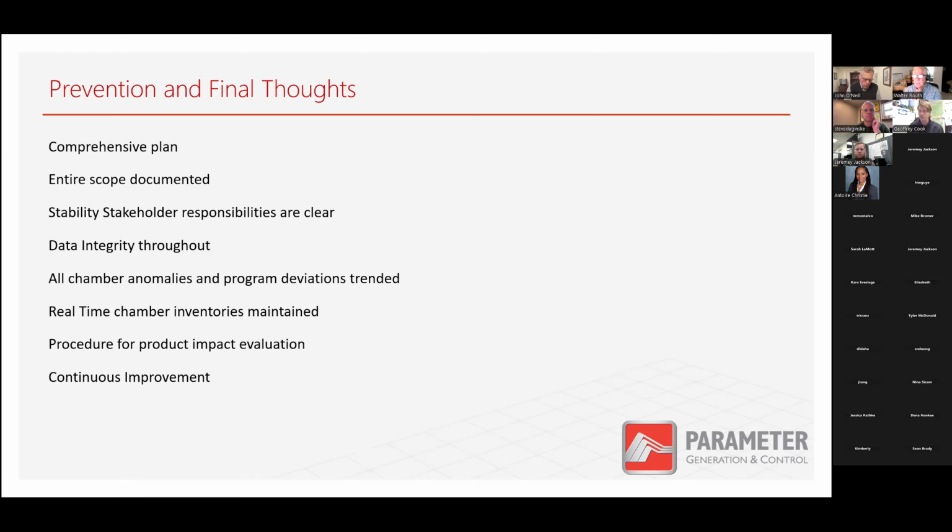a component failure. We have good documents on the expected life of all the parts, the motors, the pumps, the heaters. The life of those parts is often dependent on the conditions you're running. A 40/75 chamber will deteriorate some lesser metals over the course of years, over the course of studies. So it's very important to note all that and plan for it ahead.